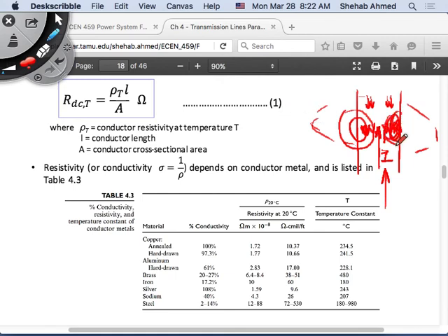And there's a corresponding increase at the surface of the conductor. There are currents opposing it in the center, but there's nothing opposing it on the skin of the conductor, right? So that's sort of the summary. That's basically what happens due to skin effect. The currents in the middle oppose the main current and push it to the outside.